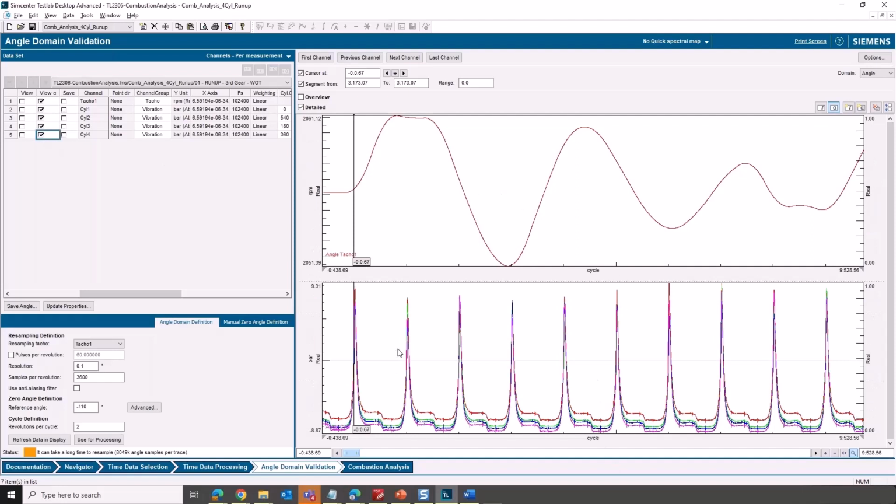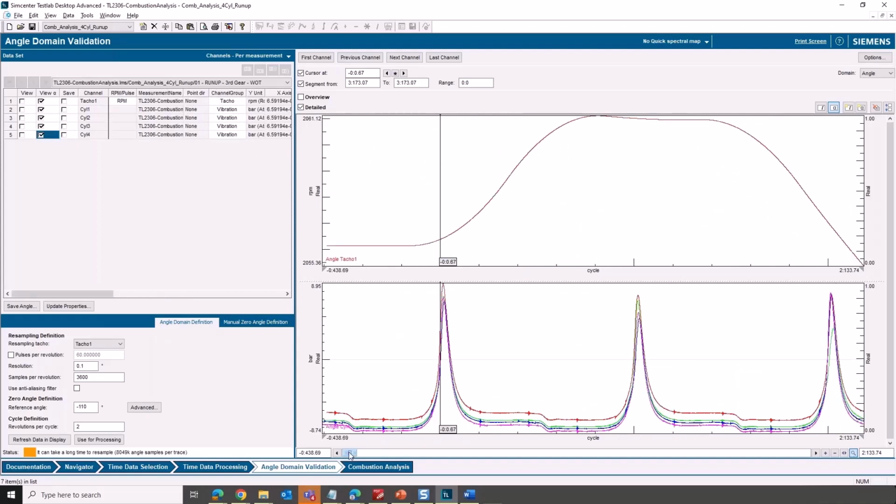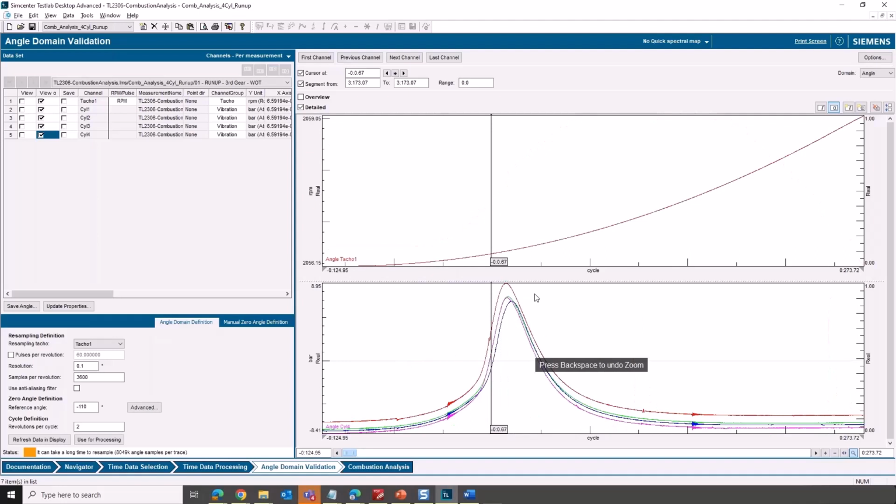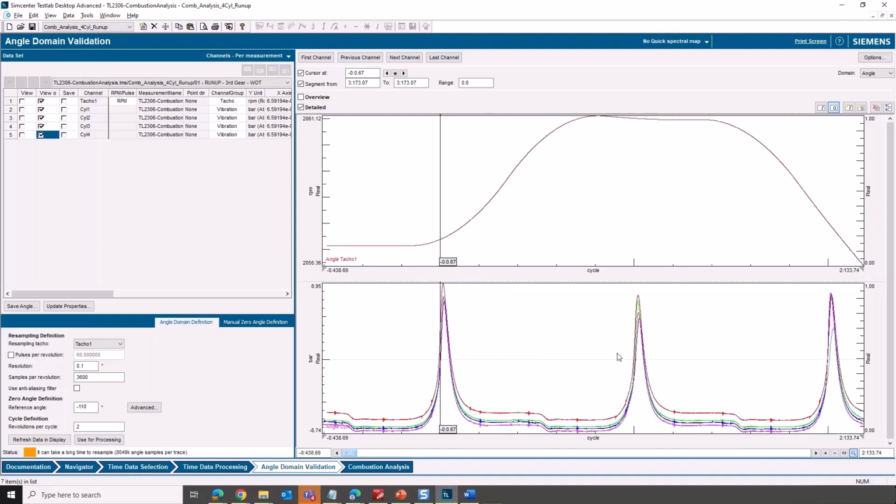Yeah. Now you can see that the 4 cylinders, instead of being not aligned, they're on top of each other because we specified this cylinder offset here. If we zoom in here, we'll notice that even within this, for one cycle, the cylinder pressures are not exactly the same. And that is why we want to look at each cylinder's performance. Here, once we have specified this cylinder offset, and we have aligned the cylinder pressures, now we are ready to do some further analysis on that.